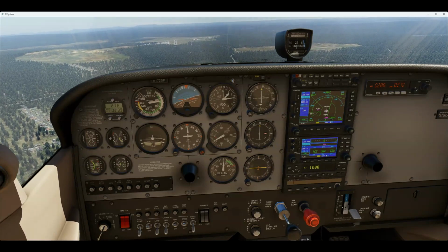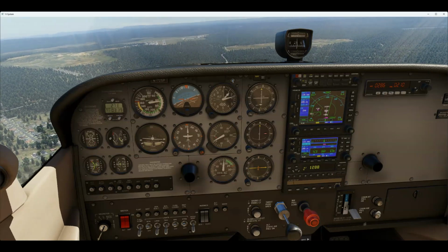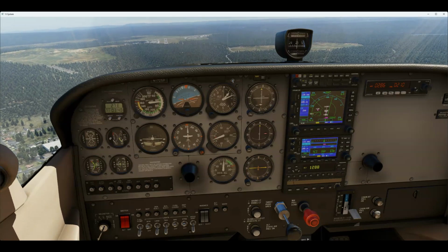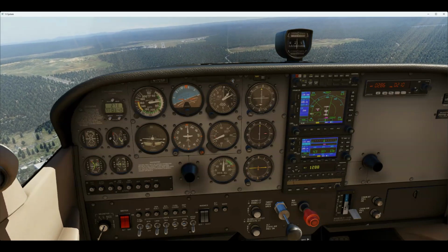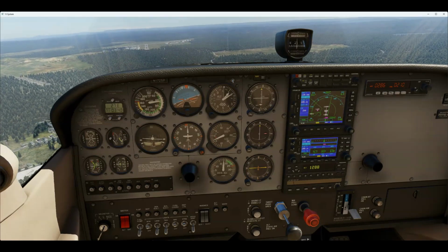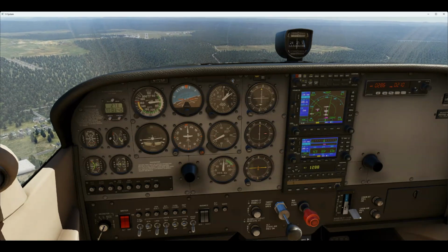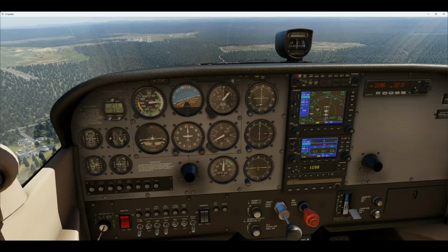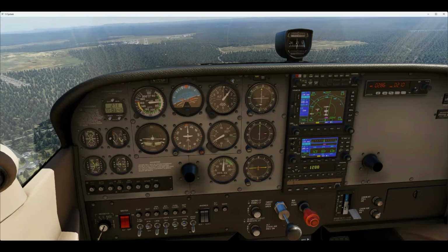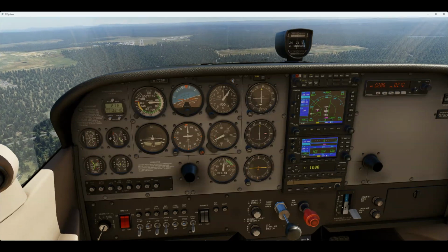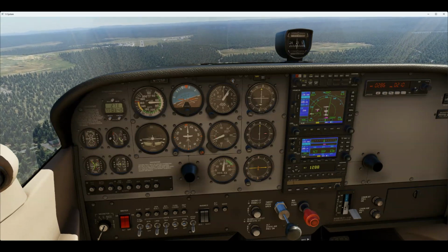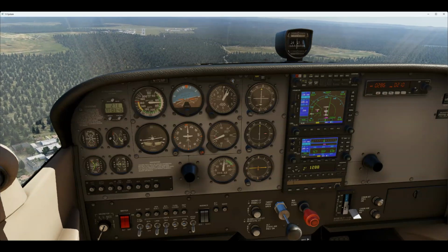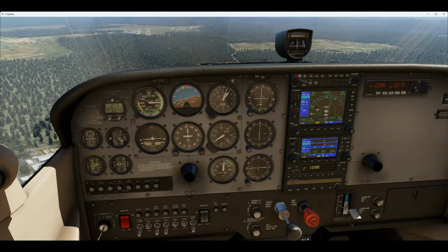I don't know if I programmed on the brakes, it'll be interesting. But anyway. Okay, you can see 211 on the GPS is what I'm aiming for. It actually says a bit of a right turn, but only a degree or two. So I'm doing like 3 degrees over the 211. So that should bring that back in. The glide slope's basically on par. The localizer is telling me slight right. It's coming in now. It's telling me now to descend a bit quicker. So I'm descending a bit quicker.